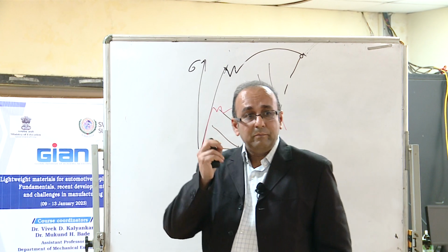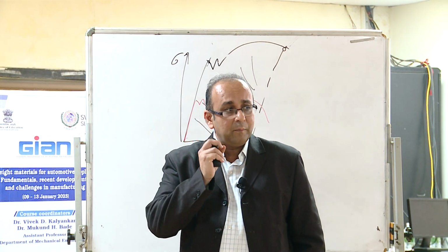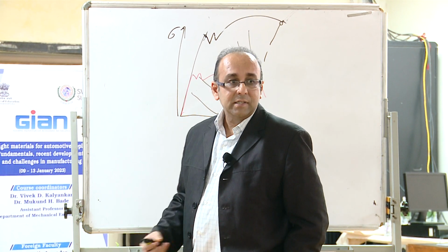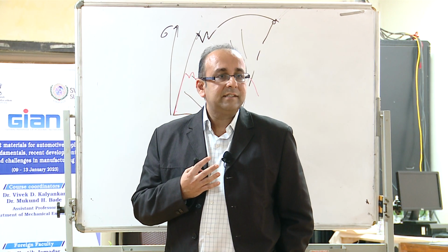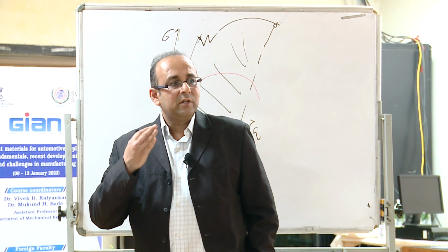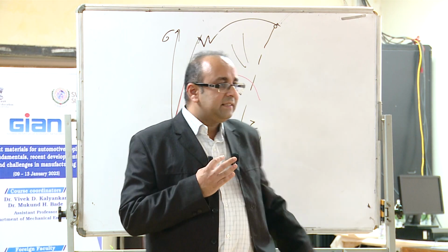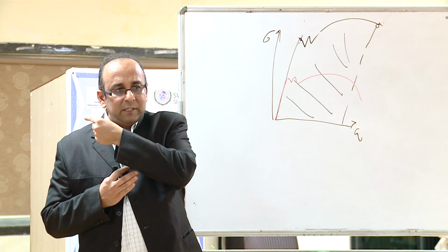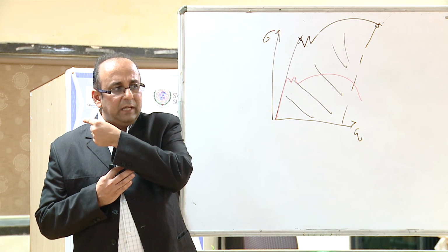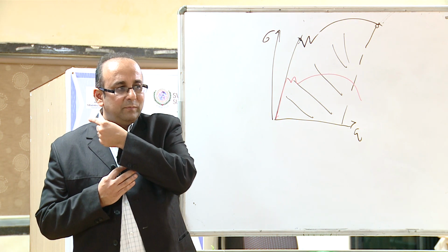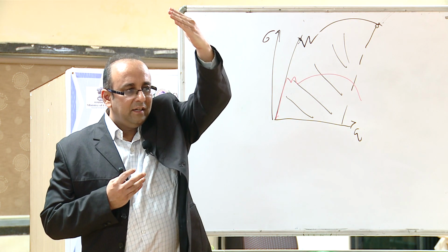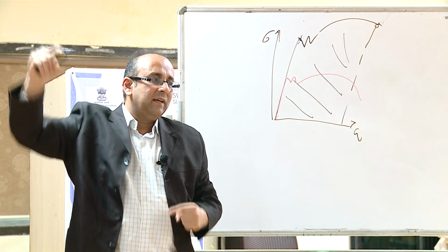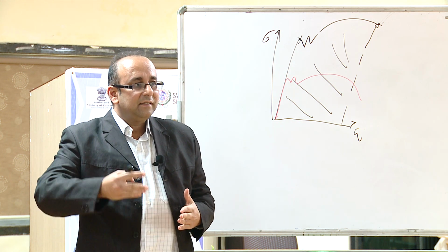The austenite being so good a deformable material, one could practically go up to 100% deformation with this kind of steel. And extremely high strength. Means I am getting this. But just imagine who will deform this material. You will need such a big press to get that force because the strength is very high, the strain hardening is very high, and the elongation is very high. Your force increases exponentially.